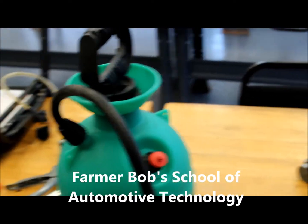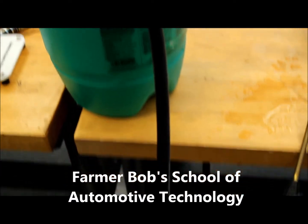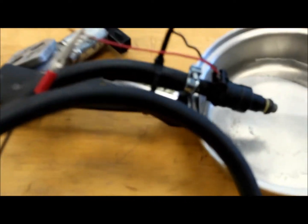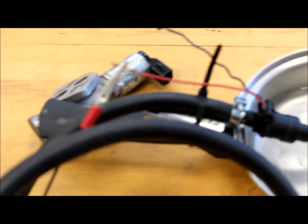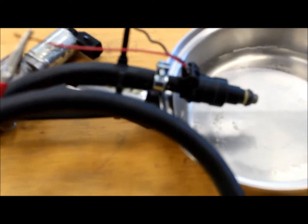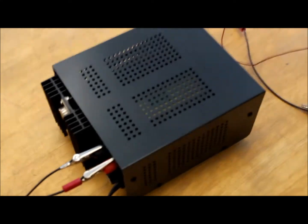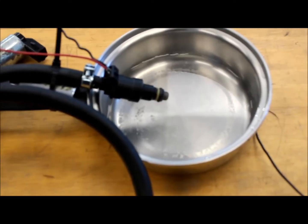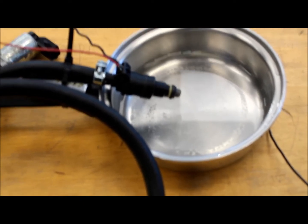So here I have my pump sprayer. I have the hose connected to the input of my fuel injector here. Let's try to focus that in a little bit better. Nope, not gonna. And so I've pressurized it. I have pressurized water available at the inlet to the fuel injector. So what we'll do now, I have that hooked up to my 12-volt power supply, and when I turn that power supply on, we should be able to see something come out of that injector.